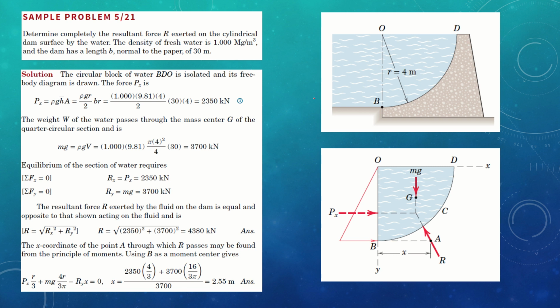You are going to use the same technique of curved surface. How do you find it? Number one, you have to find the pressure based on the x-axis, as the pressure changes as you move. Let us draw this Cartesian. This is your x direction. This is your y direction. You should remember as you go down from top to bottom, the pressure increases.